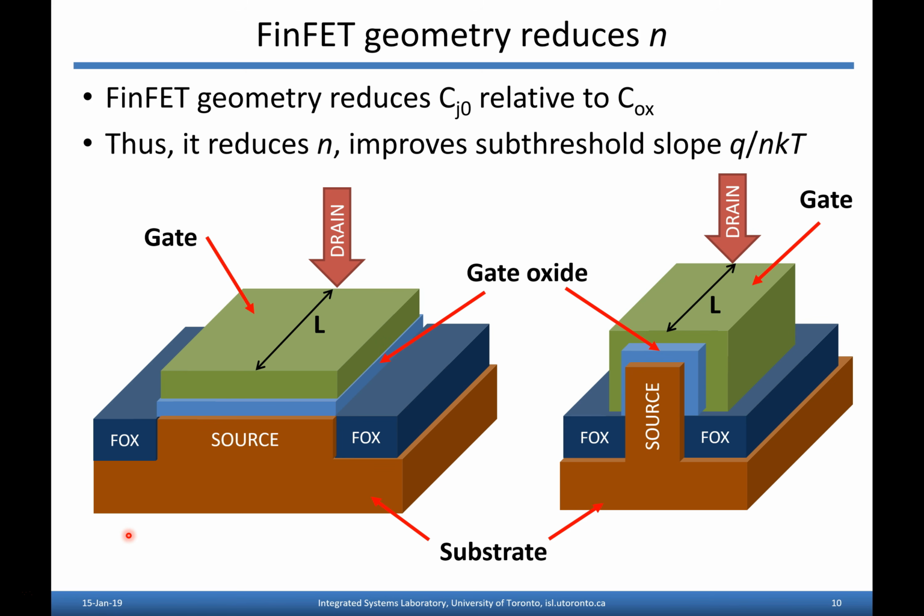So here's just a cartoon picture to help illustrate that, right? This picture is maybe turned sideways compared to the way you often picture it, but here the gate length is in this dimension here for the planar MOSFET. The idea is the drain is back here and the source is at the front here, right? So the current's actually flowing this way in the picture. N is some parameter that we said is about 1.5 for a planar device.